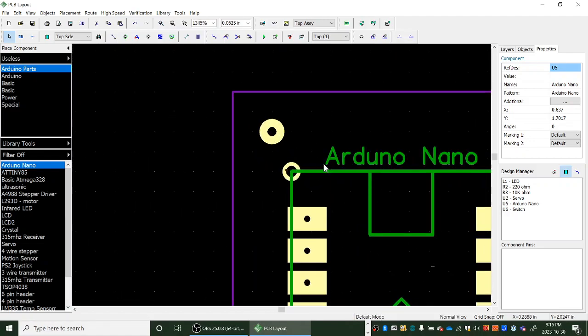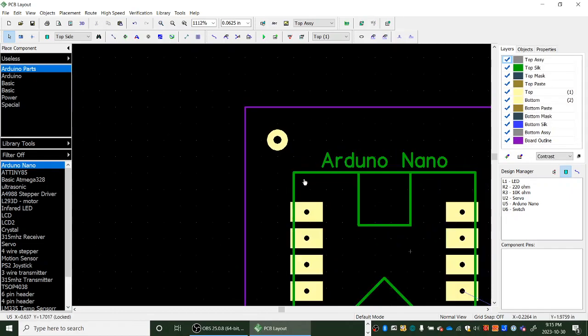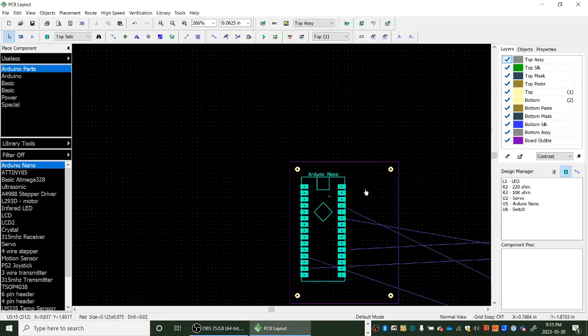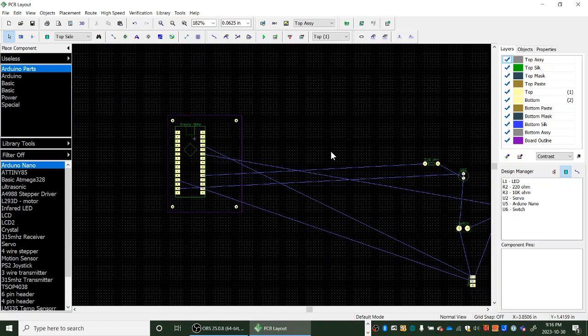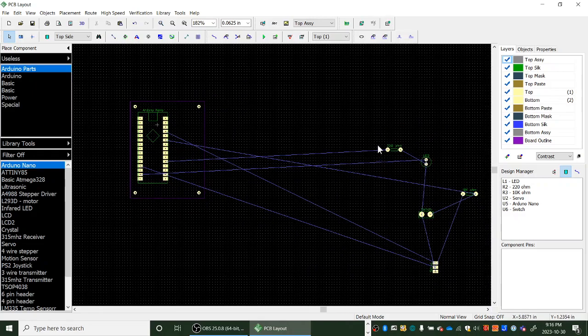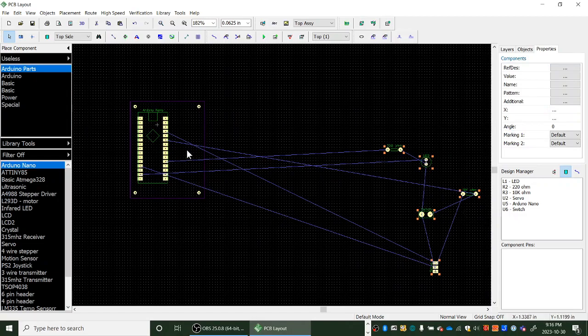The last thing we're going to do is delete this little donut. So click it with your pick tool, and delete on your keyboard should get rid of it. Okay, that's most of the setup. Now the next thing we're going to set up are the things we need before we do something called routing, or routing, if we go with the American pronunciation. These are going to have traces that connect them on the board, little copper traces. So we have to do some setup to make sure that's done right.